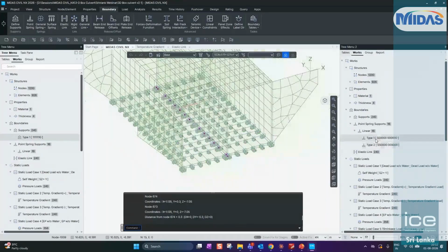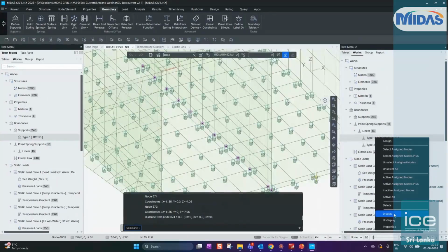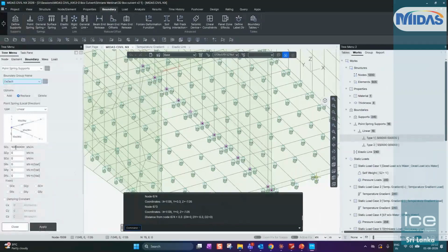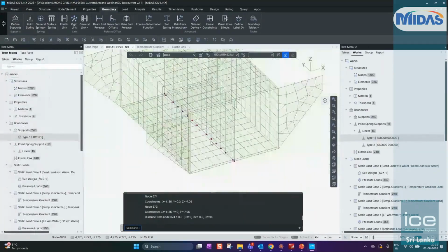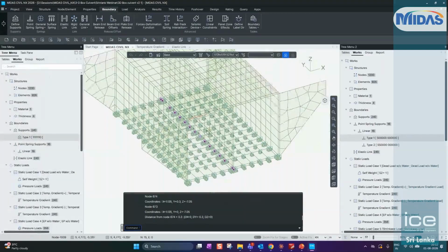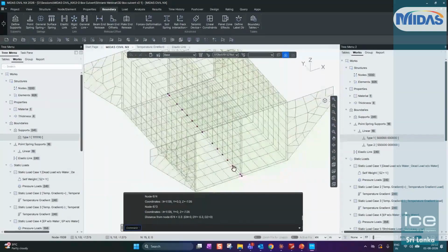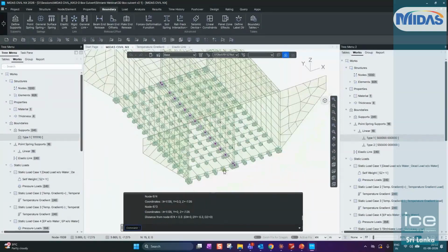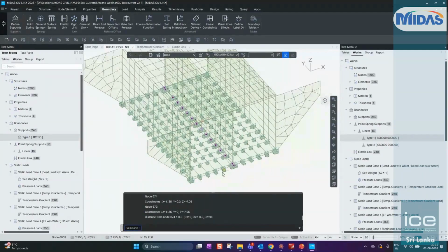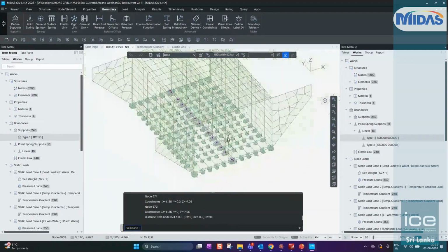So, for example, these particular nodes are assigned with spring supports in x direction, right? Or the spring supports with very high stiffness in x direction. Okay, x direction is the global x direction. So what this is doing is making your structure stable in x direction, so that the structure will not slide. Why? Because when we define these elastic links, we only define the axial stiffnesses in these elastic links, and they have no resistance to any lateral forces arising from the loading.